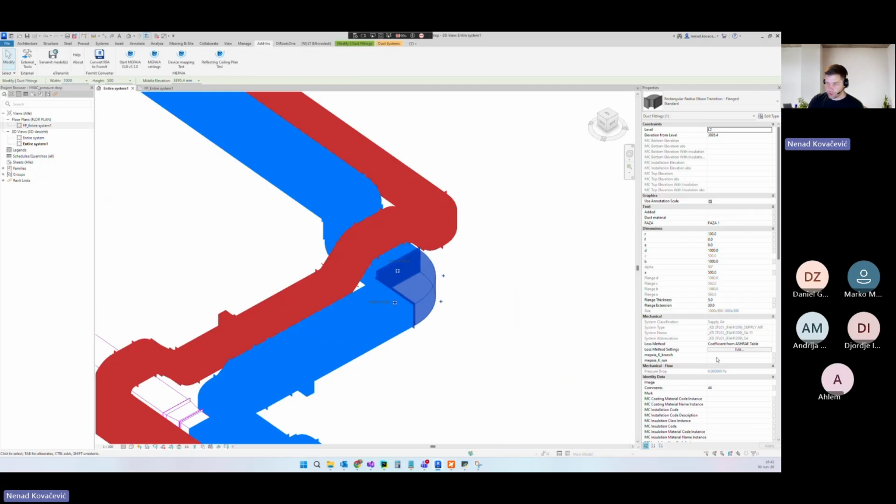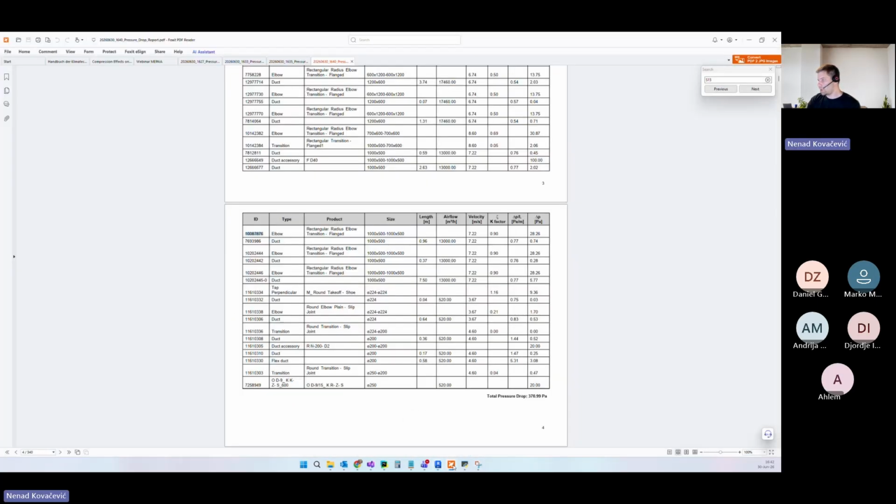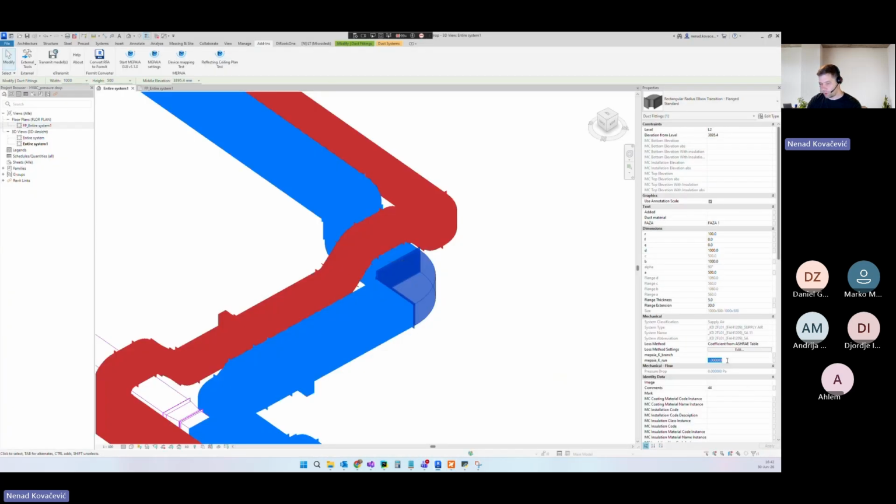And we want to foresee basically the most complicated thing, which is the T, because T and the tap have the run and the branch. But when you're creating a parameter in the Revit, you cannot create sub-divisions. Basically, you say this parameter will be for the entire duct accessory. So over here, of course, for an elbow, you will say, okay, for this elbow, what is the current value? 0.9, I want it to be 1.2, for example.